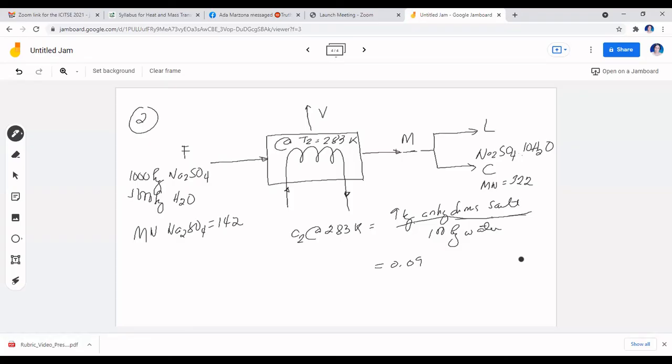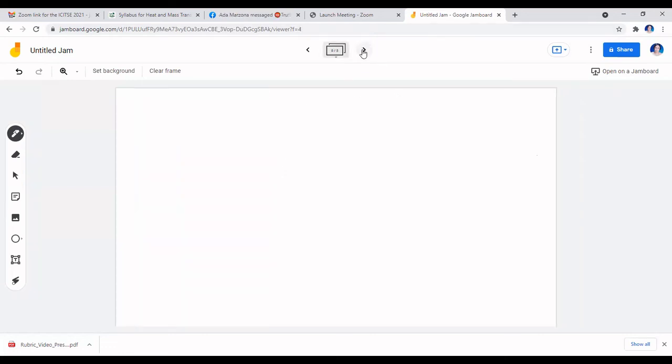So this is 2%. You will have here 2% water coming from the feed, of course. 2% of water being lost during the process of evaporation. So this is our given, and we are required to find the Y. Since we have derived already the Y, there's no need for you to do balances. So we go straight to the formula of the Y that was shared to you.